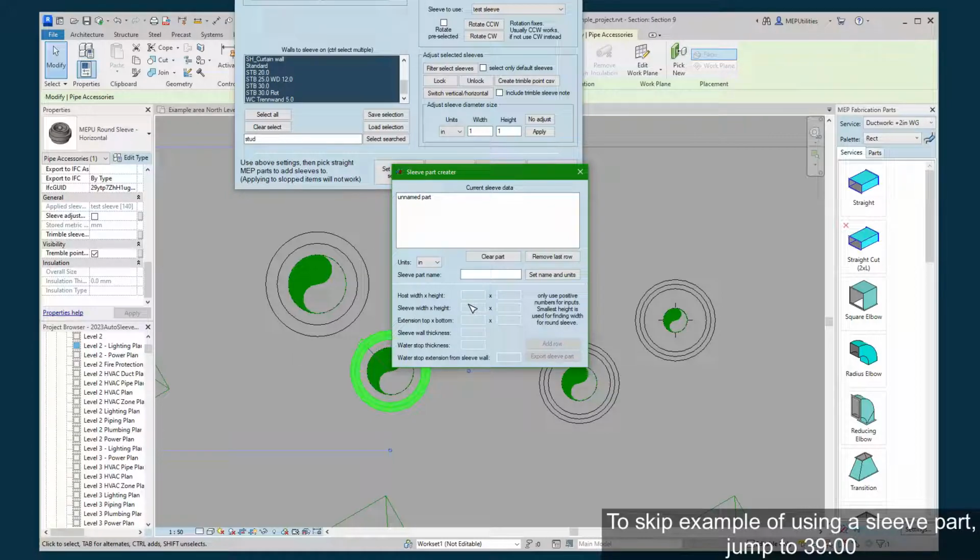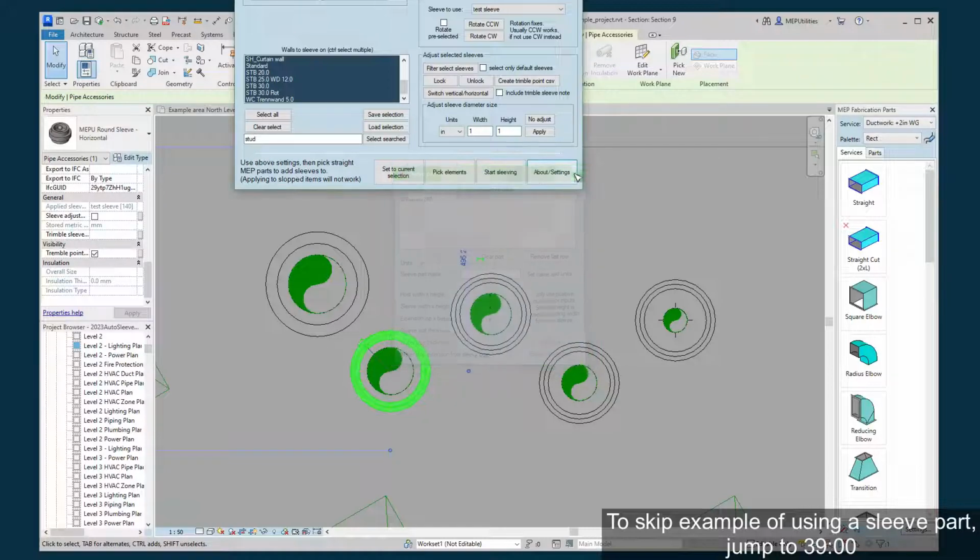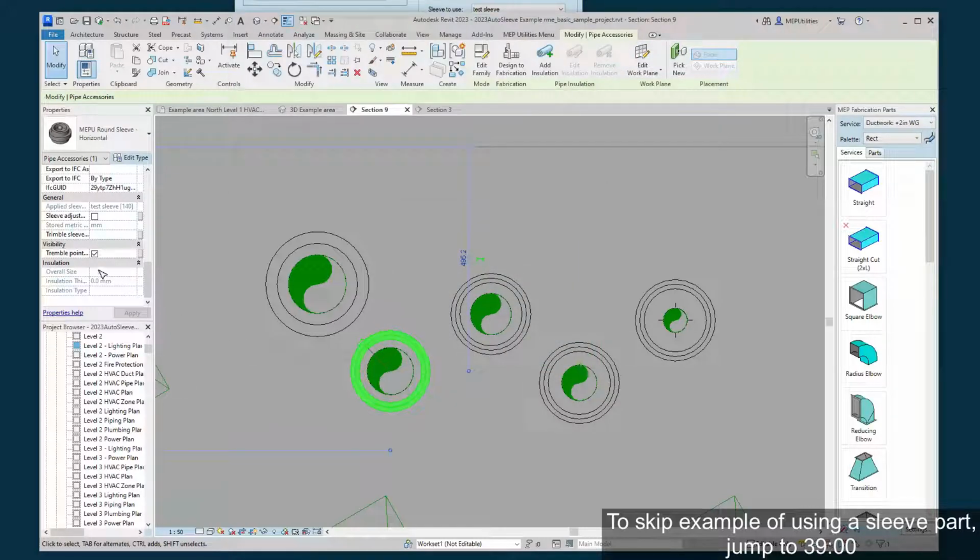And in this case, since it's a pipe, it's sleeve width that it's using. So it's a 140. And if we ever make adjustments to it, it'll be 140 adjusted by a certain amount, but you can lock the adjustments so you can't do that. But you'll note that it's 140 in millimeters, so if you're ever worried about whether this 140 is in inches or millimeters, well, the information's right here.